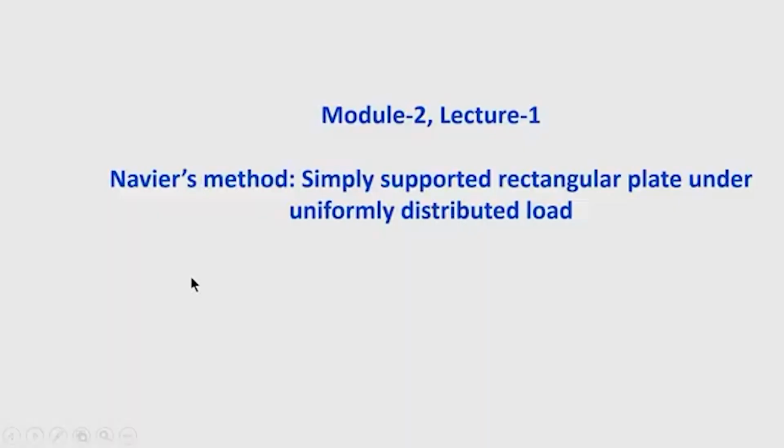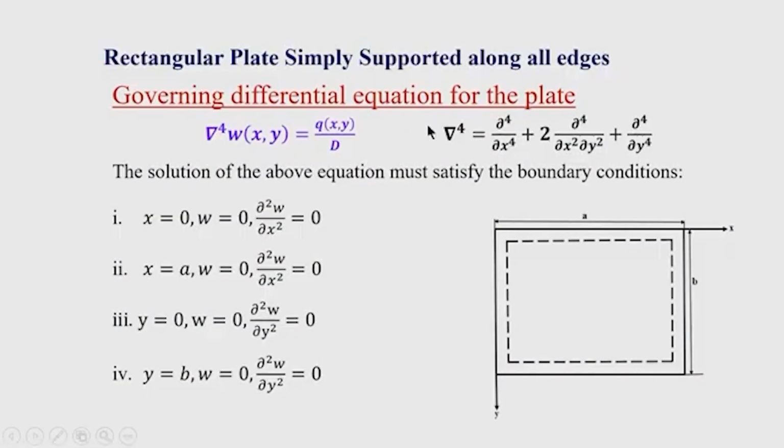Navier's method is applicable for plates simply supported along all edges, and it is especially applicable for rectangular plates. Today I will discuss Navier's method for uniformly distributed load and also partially covered load. So, let us see the governing differential equation for the plate.